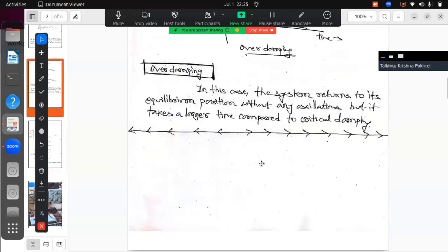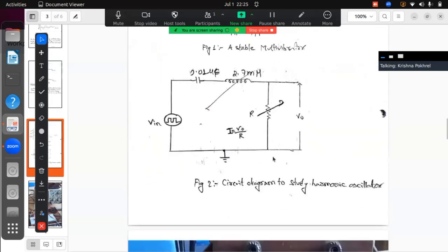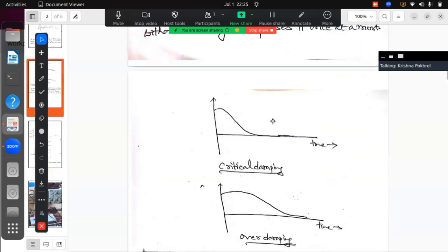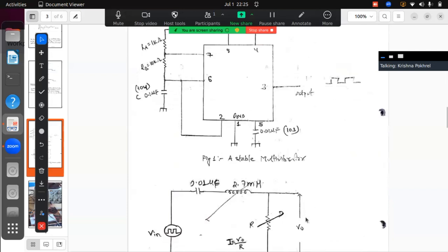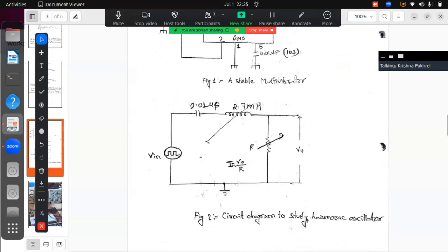But if I move further from 1000 to 5000 ohm, then we can get the condition for overdamping. One thing I have felt in our practical lab, I'm going to discuss over here: this rheostat may have some error. I have found in my lab that if I take out a 200 ohm resistance, then this resistance box shows infinity resistance, because there is a gap, because the instrument is too old. So make sure that the resistance box is working very well.